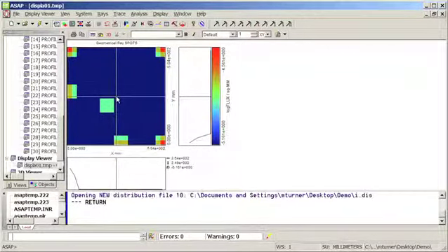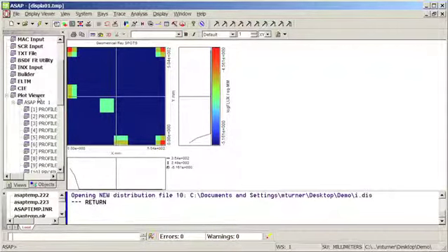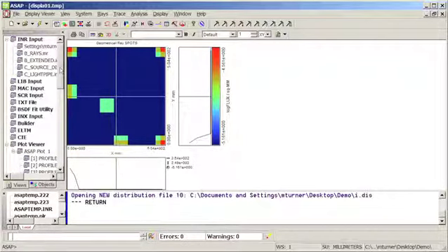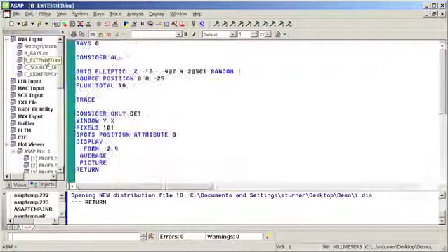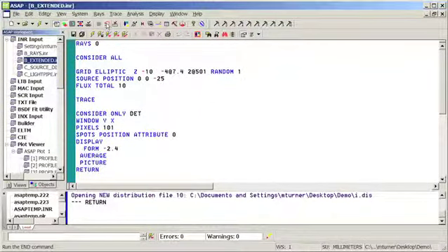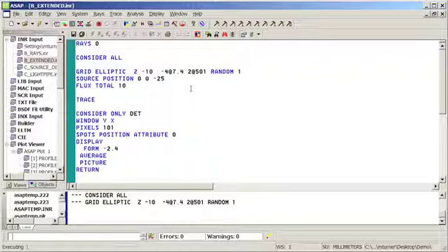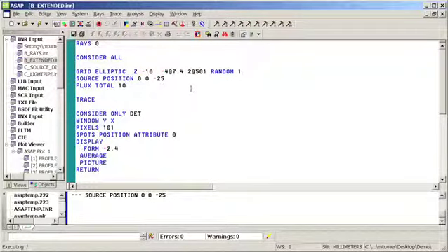You'll notice that central ray didn't quite make it to the center, but the rest are very, very close to the targeted position. But of course, this is simply for several rays coming from a point source. What we also might want to look at is what's the distribution of energy on our detector surface from an extended energy distribution. And I have another file that will do this here with a randomized distribution of rays. So what we'll first do is get rid of those 6 rays and then launch a randomized grid of rays and take a look at the output.